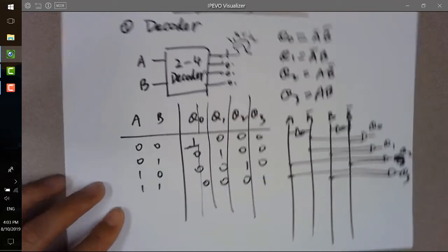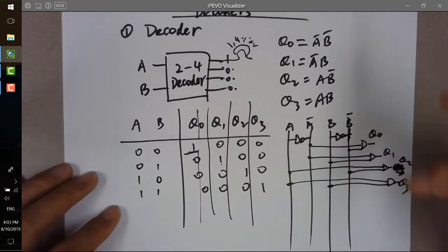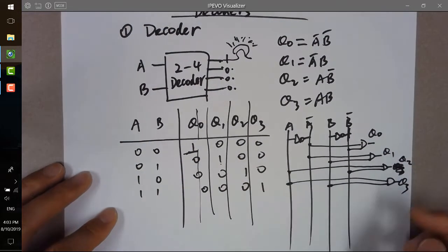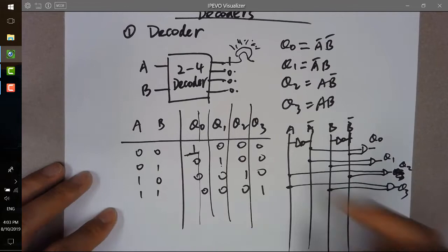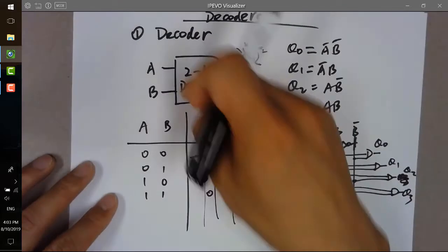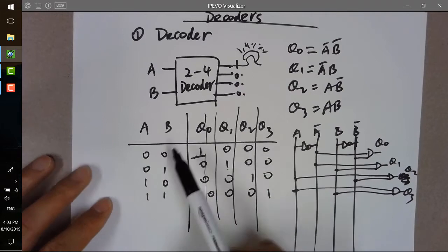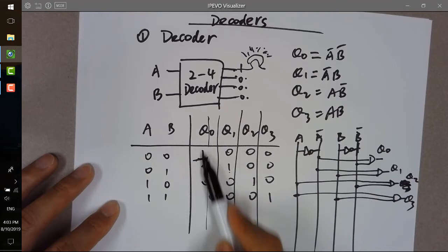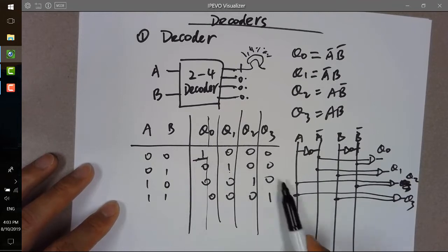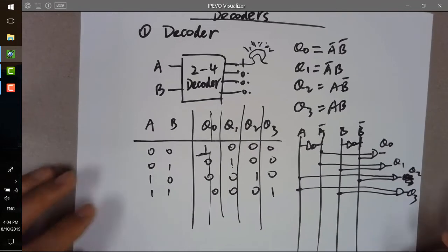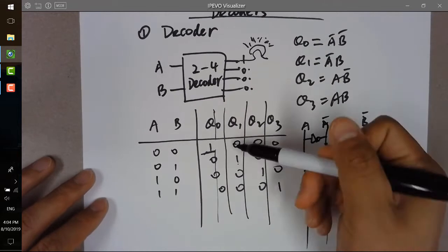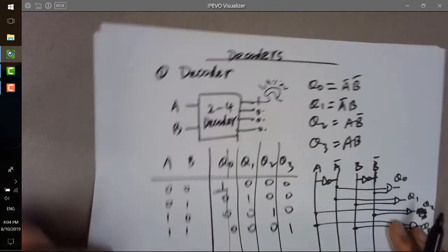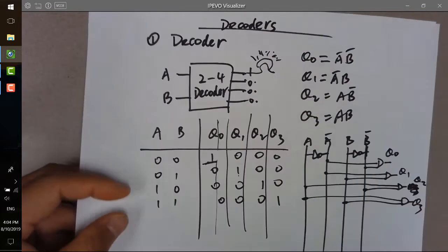That's it. And keep in mind, you don't have to use this pattern for every output. You can have any pattern over there, but the limitation is since you only have 2 inputs, you can only have 4 patterns totally. It doesn't have to be only one logic high being shifted to the next digit. It can be any pattern, but only 4 at one time for this decoder, since you only have 2 inputs here. All right. So that's the decoder.